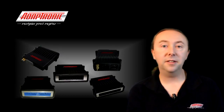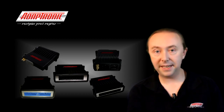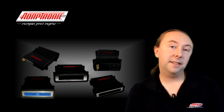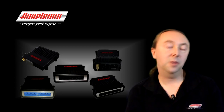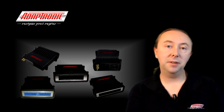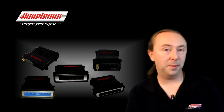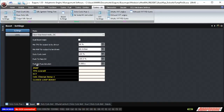If you want it to use the actual value that's in the map, then you'd set the maximum value to 100%. Otherwise, if you set it to a lower percentage, then that's what the duty cycle will be limited to. Now, on some systems, having a fixed duty cycle might actually make the boost not constant when you actually want it to be constant. For example, if there's a boost taper due to the actuator not being strong enough, like I described earlier. In that sort of situation, one of the target boost modes will probably be more appropriate for what you're doing. Now, the final setting that I'll talk about is the push to pass button.